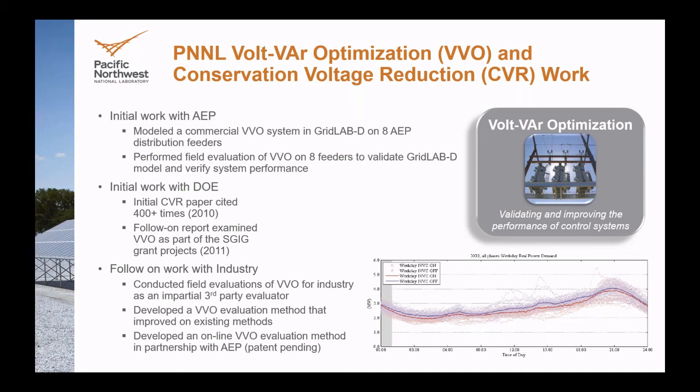It was fairly early in the GridLAB-D development realm, where we took the real-world utility models, did the annual analysis, and then after they deployed the system, our results nearly perfectly, well, perfectly within the annual uncertainty realm, matched the results of the actual CVR or Volt-VAR optimization deployment, showing something like a 3% energy reduction or the peak reduction at certain times in the year.